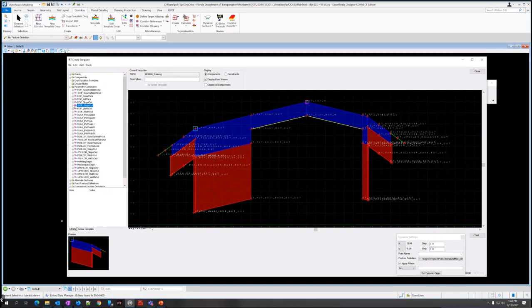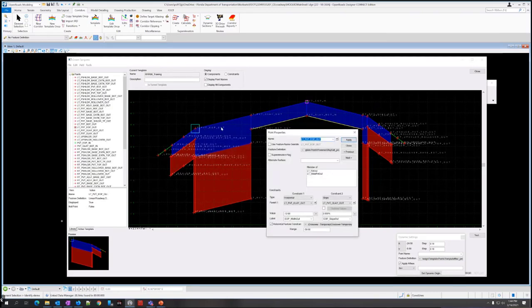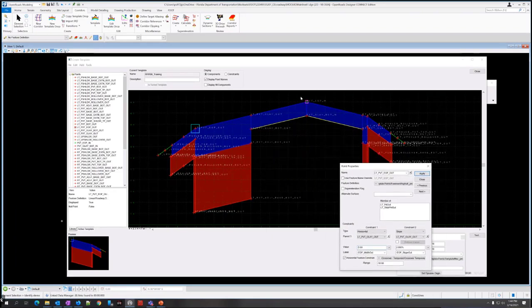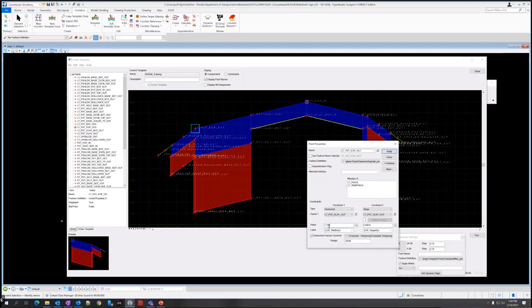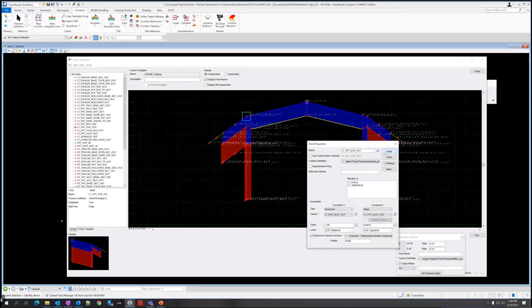So that's 2%. And then I'm just going to go back here and double click on the point to make the edit for the slope. So that should be -1. So the convention with left and right is positive and negative. So positive is to the right of the template origin. So that template origin is 0. X and Y values is 0. So it's like a graph essentially. So when it's -1, it's just to the left of that origin by 1 foot.